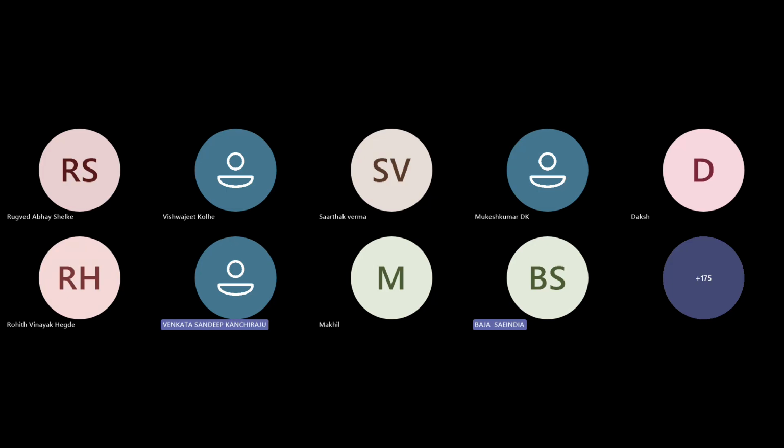That is actually where your differential ratios will be. So the gearbox ratio will be different, and the front differential splits the right and left. It has a certain transmission efficiency and also a ratio. You have to mention that. And for the front axle, we don't have any option called open. You can use a locked or viscoelastic.